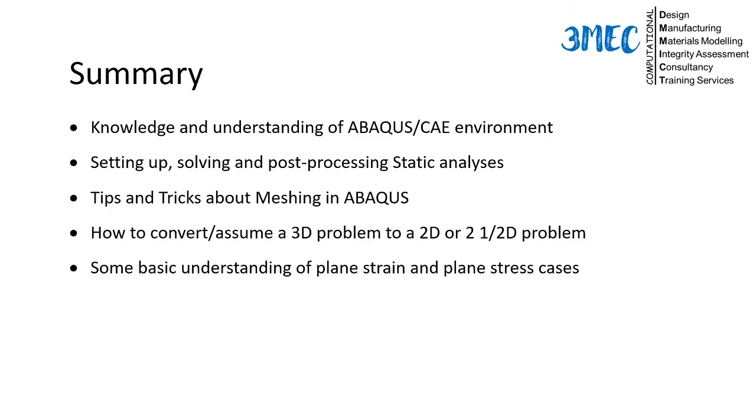So hopefully this session would have given you a better understanding of the ABAQUS environment, how to construct the models in 2D and 3D. Well, I normally say 2.5D because I prefer to say that if you're using plane strain or plane stress cases. So you learned about the setting up of the model, solving the static analysis problem, and how to post-process the results. I tried to give you some tips and tricks about meshing. ABAQUS is not an expert mesher, and sometimes people use other meshing software like HyperMesh, etc. So you can look into that if you have complicated geometries. I also showed you how to convert or assume a 3D problem to a 2D or, strictly speaking, 2.5D problem.